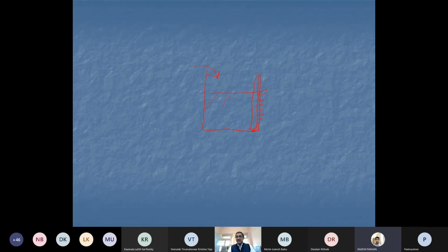You are measuring the head that is coming through channel, passing over the crest, that is also a stilling basin. There is connected somewhere and there is a big reservoir kind of a stilling basin, but here it is simple tube stilling basin. Water level is same and it is well calibrated that if this is the level, this is the amount of water in this.